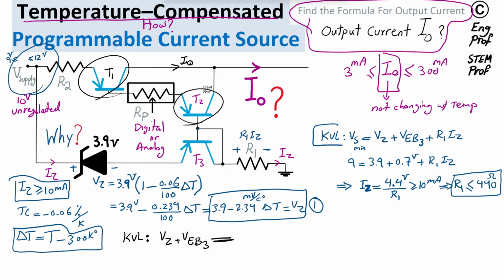Combination of T2 and T1 effectively is in Darlington formation, while T3 is effectively just a diode formation. So assuming T1 is carrying up to 300 milliamp, let's say we just set it to up to 500 milliamp at least, it's a mid current size transistor.